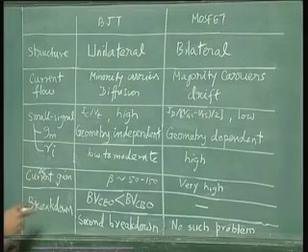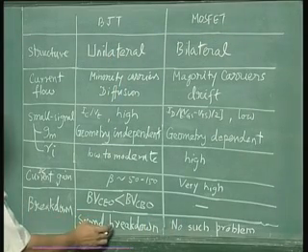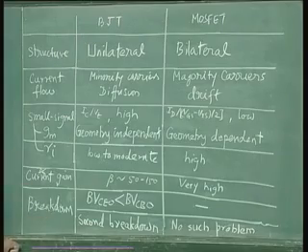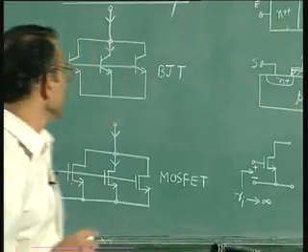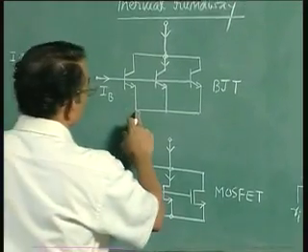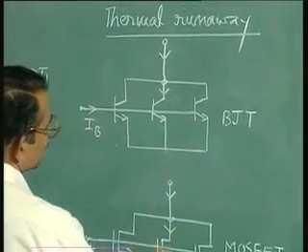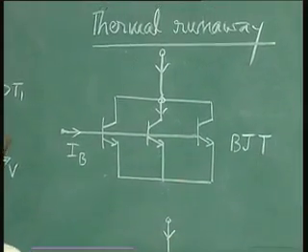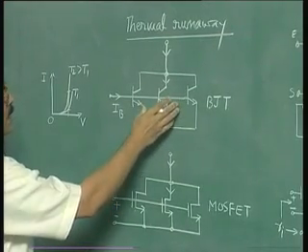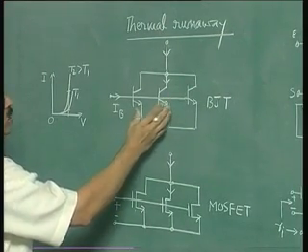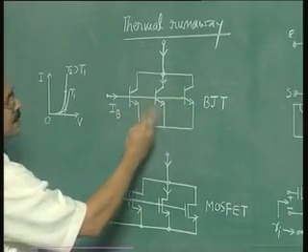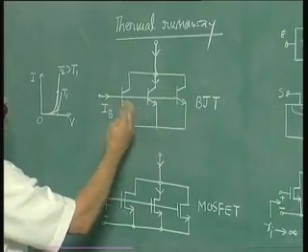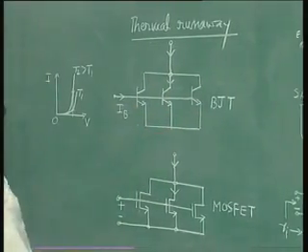A very important thing that we should consider related to breakdown is the mechanism of second breakdown which afflicts the BJT. Let us understand this mechanism with reference to the diagram here, which shows a parallel combination of devices. This kind of a parallel combination is used to increase the current carrying capability. Okay? So instead of making one device with large current carrying capability, you can parallel various devices so that you get effectively a device which has high current carrying capability.